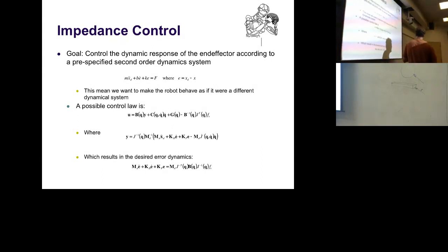Okay, so that was a quick trip into force control land. Very important. The principles we know from standard control, PD control, just get extended. But then you rethink the process and see what kind of sensors you have, what you have available, what is noisy. You try it out, you get your beatings, go back, fix your control law. But slowly you get into the right ballpark and get a complete control law going, and it's going to work in reality.